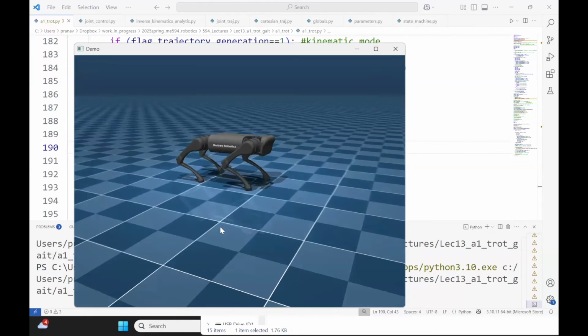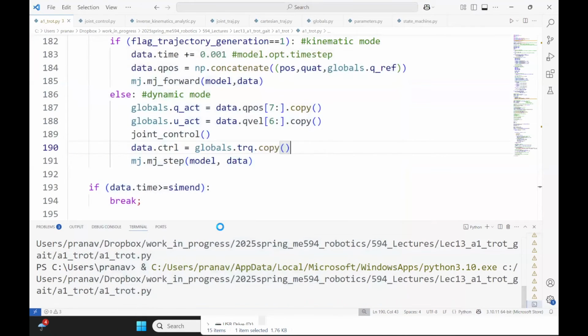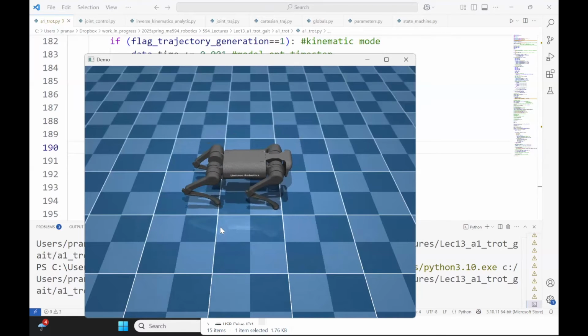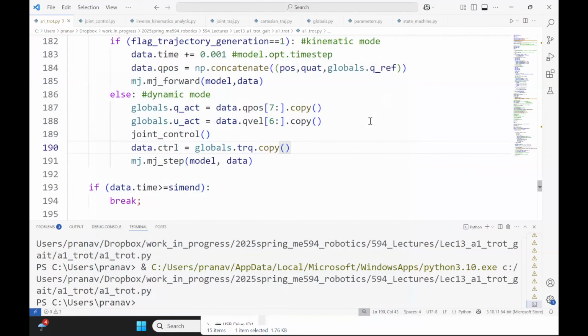It is doing what we expect it to do, which is move the legs in unison, but you can see that it's tilting the body. One of the reasons it's tilting the body is that we don't have good force control. We need some kind of force control, at least in the stance phase, because when the foot is on the ground, it has to resist gravity, and the feet hold on to the pelvis. That's missing. So I'll show you a simple way to do this, and then we'll do a fancier way, which will take care of the vibration.